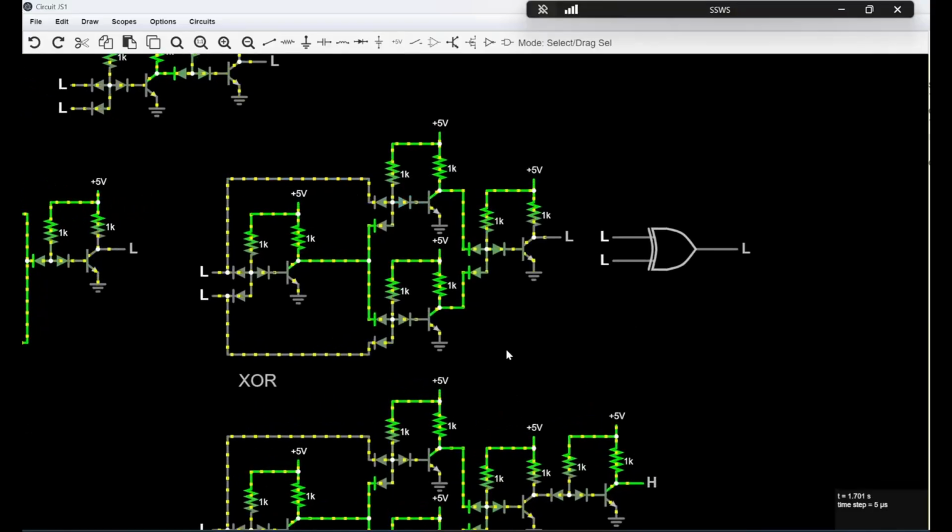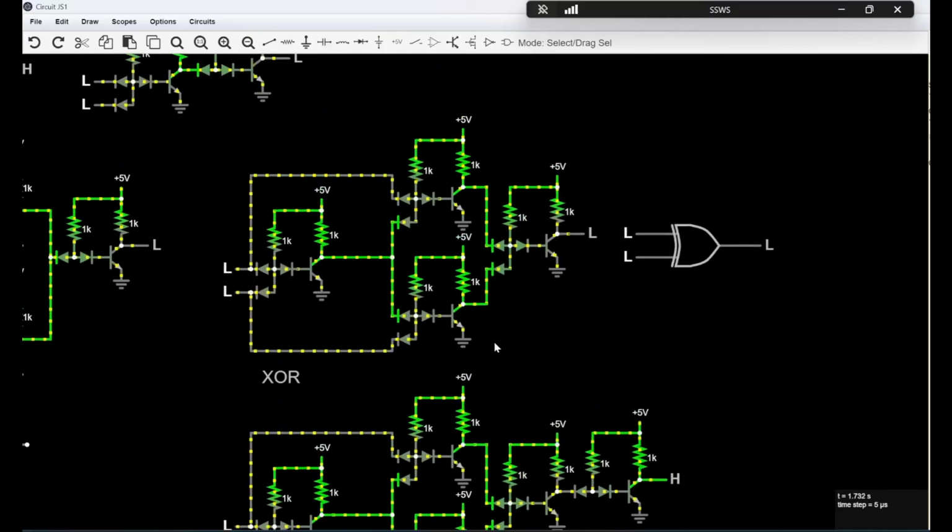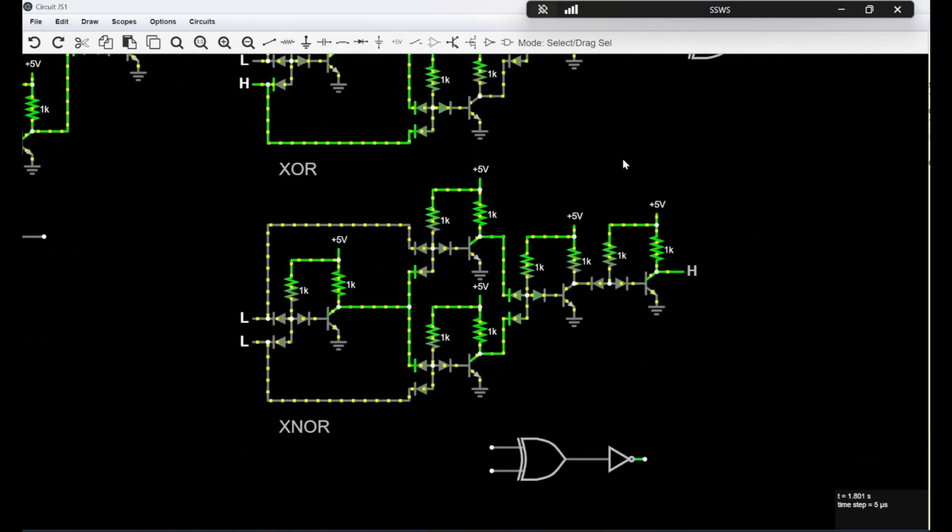And here we have our exclusive OR gate, which is the last real gate we really care about. I mean, there's the exclusive NOR gate, but who's using that? So, exclusive OR gate, it's either or, but not both. It's mutually exclusive. So high input here, we get a high output, but if we have a high input here and there, we get a low output. But let's say we have a low input here and a high input there. Oh, it's crazy, right? And you can test that with this exclusive OR gate right here. Either or, not both.